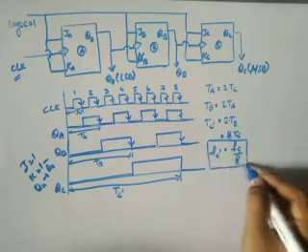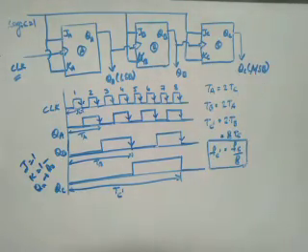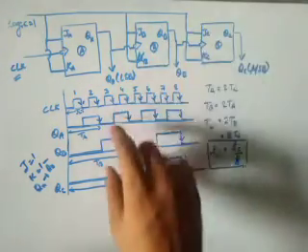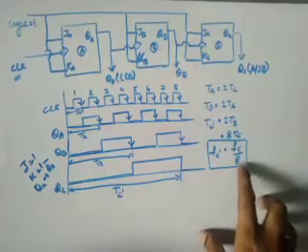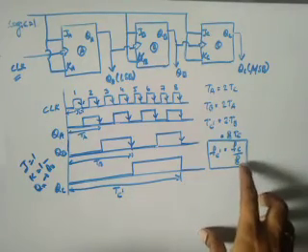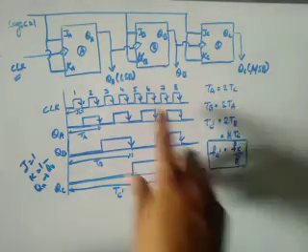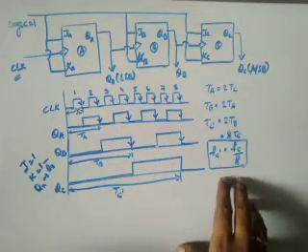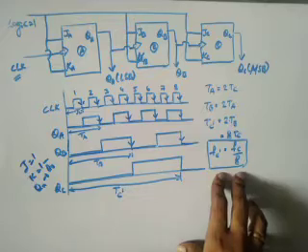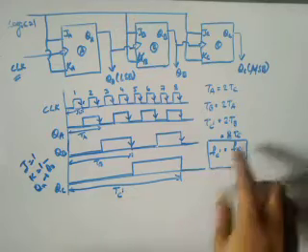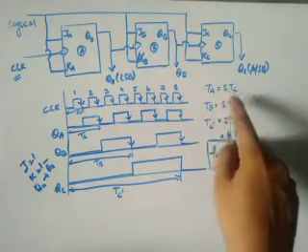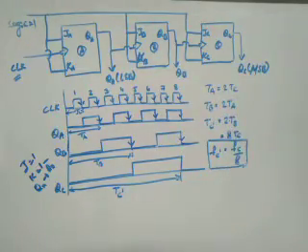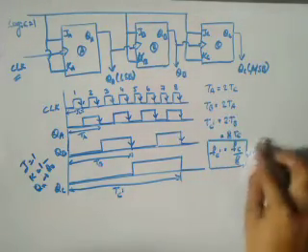So the frequency of the last flip flop, fc dash, is being divided by 2 cube, that is nothing but 2 power 3, where 3 is nothing but the number of flip flops. So likewise we can have this frequency. Please take down this on the side of your notes, or you continue in the notes. I am going to rub it now.